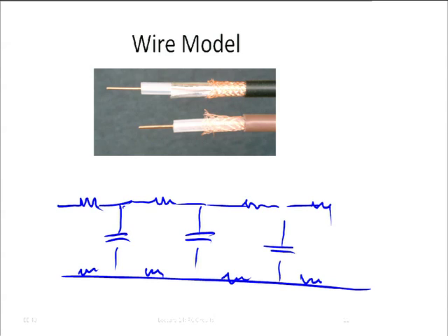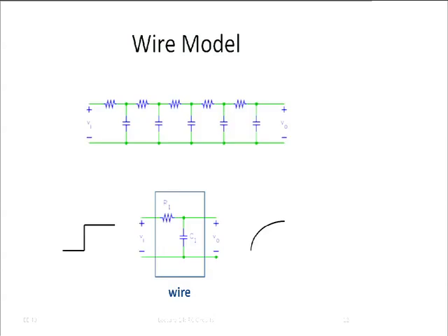117. But fortunately for 40, there is an easy way out. Yeah, this is the real model, but this is good enough. If we model the cable just with one resistor and one capacitor, then it's not quite accurate, and in some cases we make a real error, but in many cases this is fairly reasonable, especially if you have large source resistance and so on.